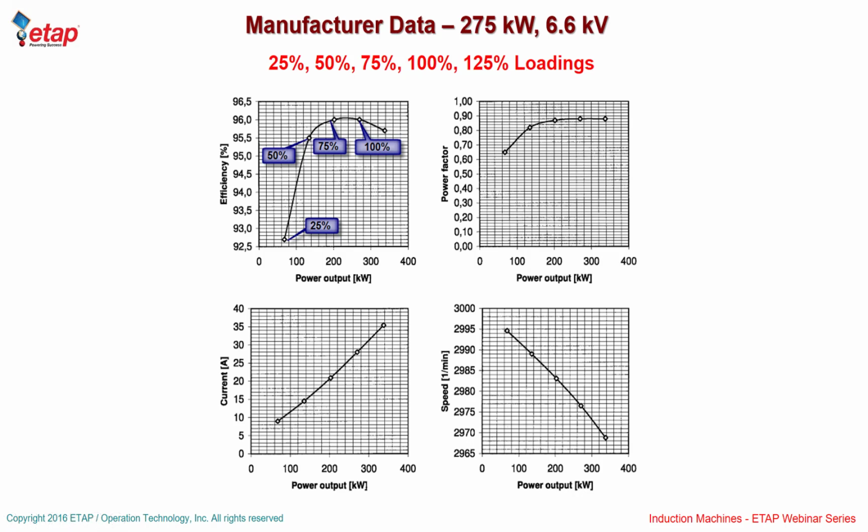And you can see the curves as is expected. Induction machines are one of the most nonlinear elements in the whole power system. They provide a lot of nonlinear behavior, and you can see the power factor as a function of loading, from zero loading to maximum loading or overload conditions. If you want to get the current, for example, and your power factor at zero loading, you can extend these curves, but you have to have these curves from the manufacturer. Especially for larger machines, you cannot just put in typical values.